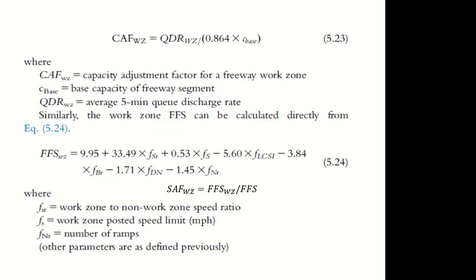So that speed limit divided by the original speed limit without the work zone gives the ratio, FSR. The second factor is the speed limit in the work zone, the one you are using in this ratio, so the speed itself. The ratio goes here and the speed itself goes here.